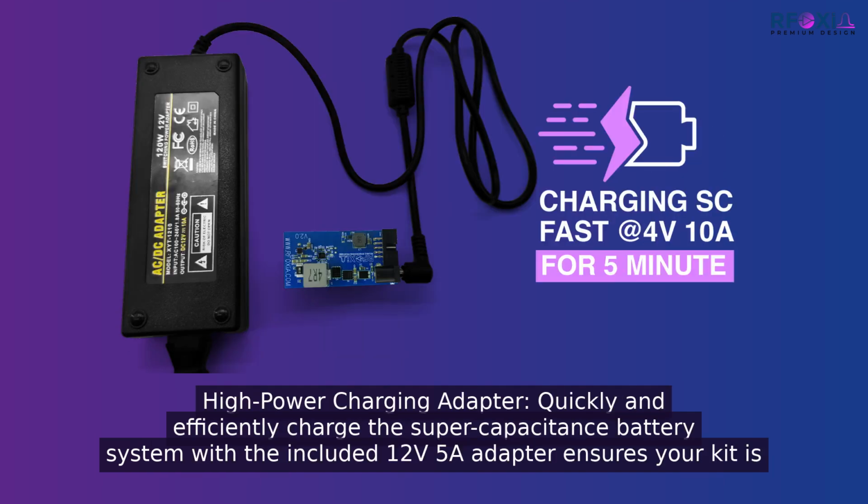This is the 12 volt 5 amp charging adapter. It charges the supercapacitor bank through a 4 volt 10 amp input stage, meaning the full 1100 farad bank reaches capacity in under 5 minutes. In practice, that means you charge once in the morning and the power system is ready for a full day of development. There is no waiting for a battery to cycle, no degradation after 1,000 charge cycles. The supercapacitor technology does not age the way lithium chemistry does.